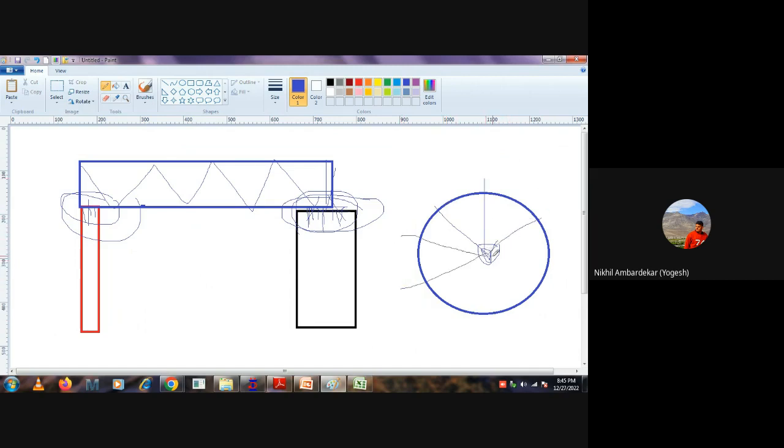So for the worst condition, we need to apply this 12.25 load everywhere on the outer wall. We cannot just apply at one location, maybe here, because we never know. So just for the safer side, apply this nodal load everywhere on the outer side and apply these 2 nodes here only, at the center part. Got what I want to say?